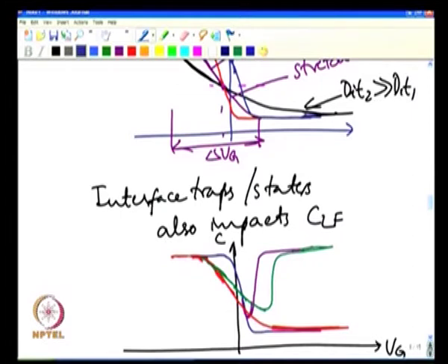this point you do not see that difference anyway, because all your capacitance is dictated by Cox. And again here this is as expected, this is dictated by the maximum depletion width, minimum capacitance, and again this is governed by whatever you have in terms of the oxide capacitance. But here where they were supposed to be exactly identical on top of each other, you see this difference, and this difference, whatever you have in this depletion region, is due to CIT. And that is what you see.